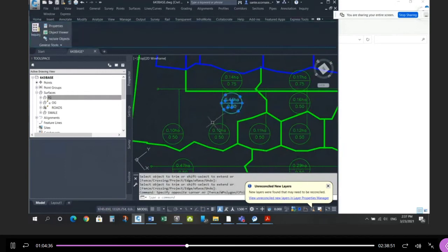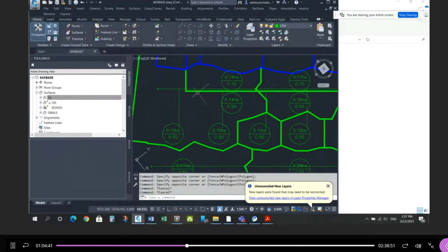So this bubble and these two backyard bubbles get combined. And now you have the total area to design this sewer pipe. We don't design these, and I'll do a calculation as to why that's done. Okay. So now we're going to combine all the backyard areas to the area that it goes to the street sewer. We're only going to put street sewers on our drainage design sheet, right? On the storm design sheet.